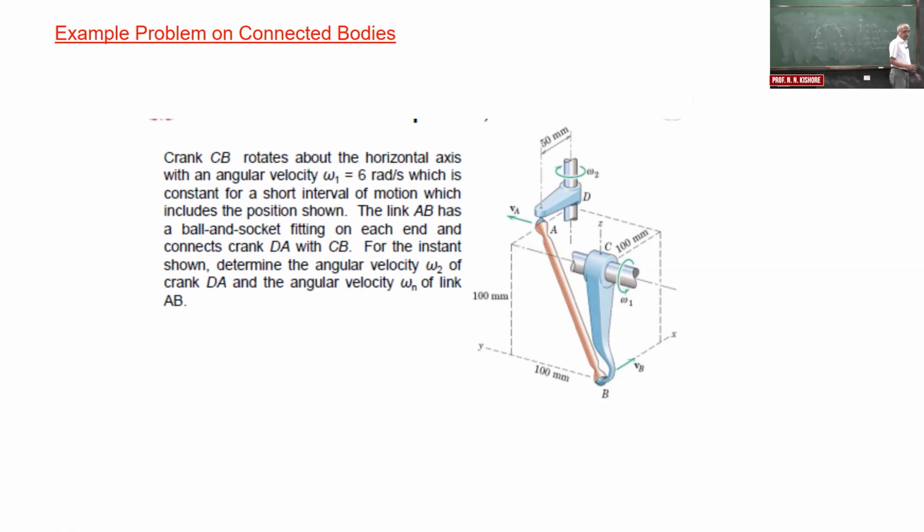In fact, the nomenclature is not exactly the same, but you can see there are four: the one crank, and then there is another coupling rod and another crank here. So we have three moving links, though we call it a 4-bar. The other 4-bar is actually D to C.